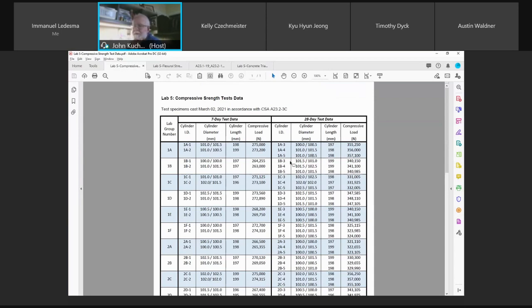Your area, okay? You're going to use the average diameter. Average diameter to determine your cross-sectional area. And you measure to the nearest 0.5 millimeter for your average diameter. I'm going to be quite adamant now. If I see hundreds, I'm going to start deducting marks. Follow the procedures, okay? I've given you these.